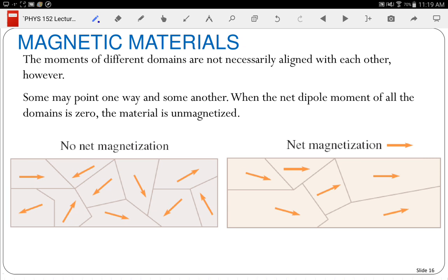Now this is not super hard magnetically. That means that it can, over time, start randomly fluctuating and losing its magnetic orientation. If you have something that's really magnetically hard, like those little magnets I gave you guys, those are very unlikely to lose their magnetism because you have to basically heat it up to get them to rotate. So that's how we can change the magnetic orientation.